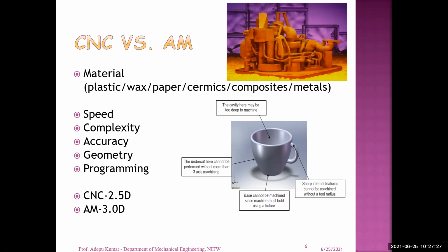The material is aluminum alloy, but the problem is that additive manufacturing is much more time consuming than CNC, so the product delivery time is longer. So you can choose depending upon the type of material and the type of complexity, either CNC or the AM process. Then similarly, suppose you go for complex nature, the latest trend is micro channels.